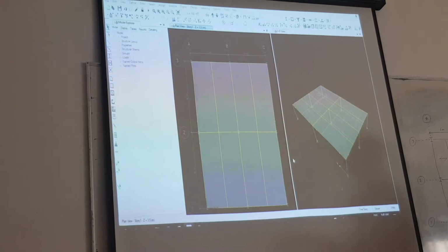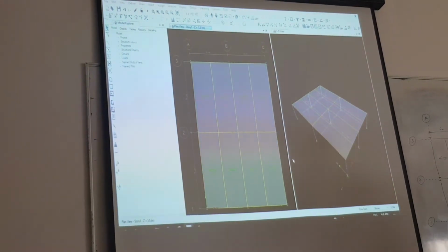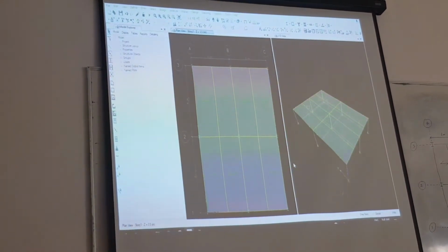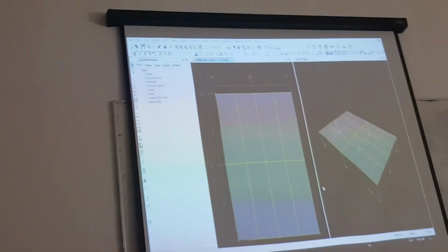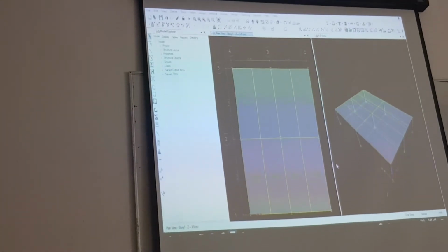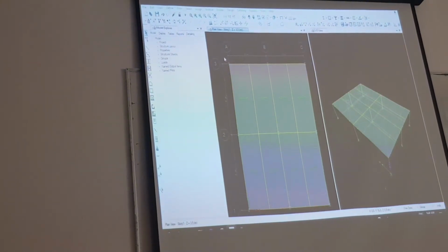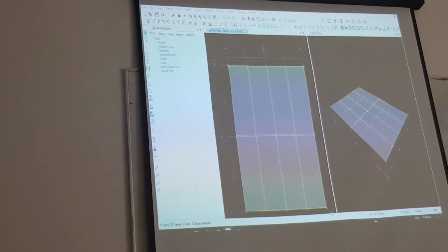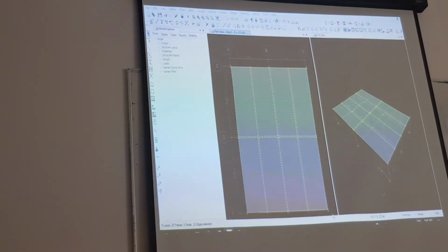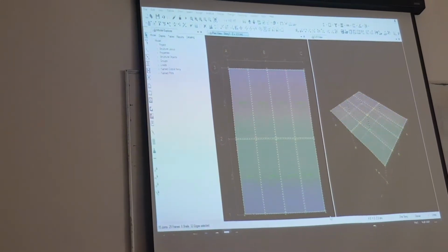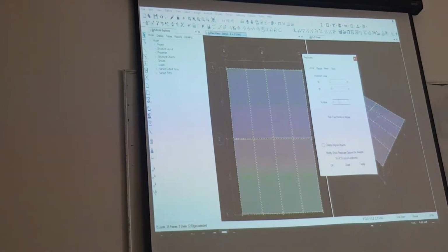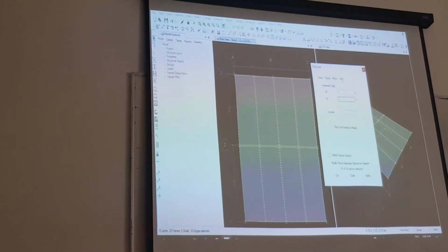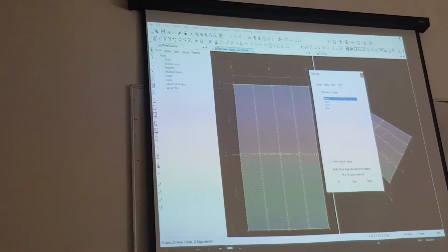What you are going to do next is that you are also going to draw for the same stories. Either you can use the same approach, but since we have this good option for replicate, this time select everything from top to bottom. Select all these things one time, okay? And replicate it. First of all, make sure that everything is 0 in the linear option. This time you are going to replicate in story.